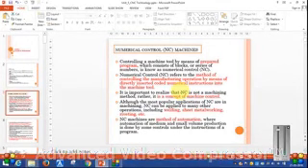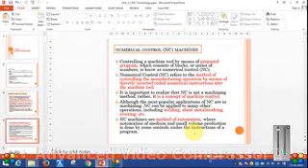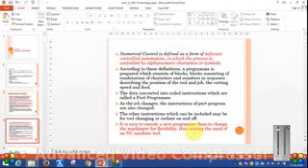It is important to realize that NC is not a machining method, rather it is the concept of machine controls. That is, NC machines are methods of automation where the automation of medium and small volume production is done by some controls under the instructions of the program. Thus we can say numerical control defines the software control automation in which the process is controlled by alphanumerical characters or symbols by using the punched paper tape.